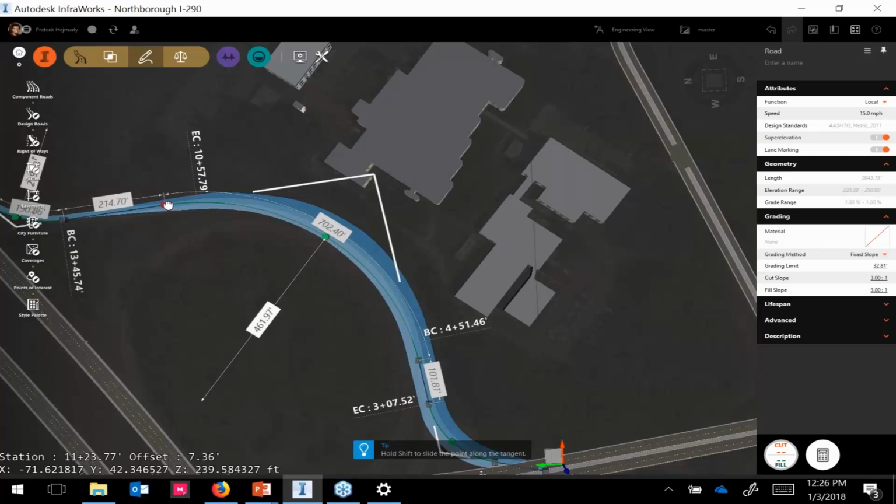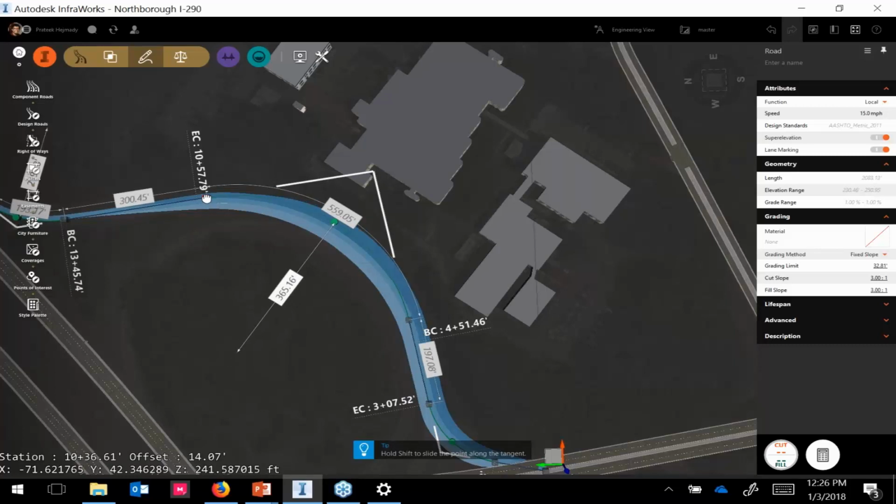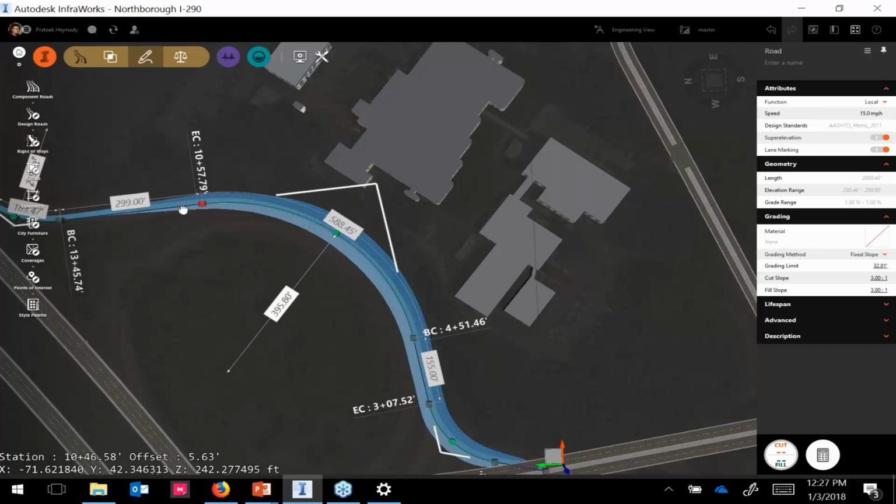So depending on the context of the action you're performing, we will be showing these sort of tips that will come up in that bottom section of the canvas to provide you with more advanced options in terms of keyboard shortcuts or keyboard enhancers to constrain the behavior. So in this case, if I hit shift, you'll see the behavior will change. So I'm hitting shift right now. It's almost constraining, or limiting, the movement that I have with that grip at this point. So that's the same behavior you saw with the center point grip, with the keyboard enhancer. So I'm going to leave it at that.